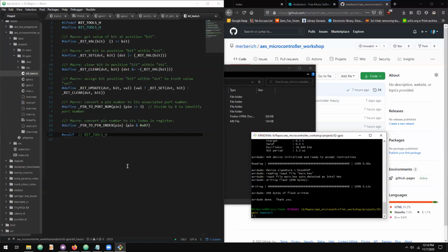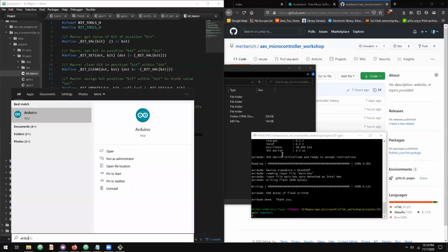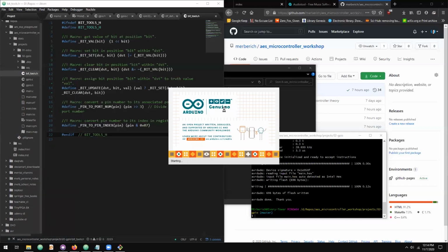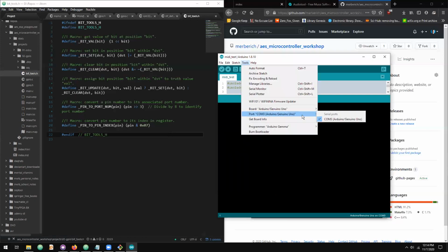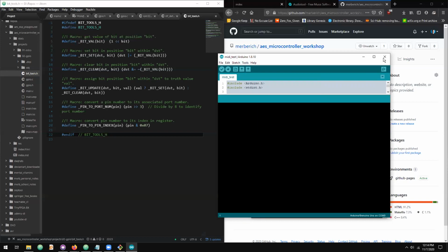Do you also have the Arduino IDE installed? Yes. Okay, so another way, and probably the easiest way to check the serial port is just to go into the Arduino IDE, do Tools, and then look at the port. If the Arduino doesn't show up there, then I'm not actually sure why your Mac isn't seeing the Arduino. I would try a different USB port in that case. Oh yeah, I'll try that. Okay, but this should show you the serial port identifier that you can use in the AVRDude commands as well. Right. No, it's not seeing it still.